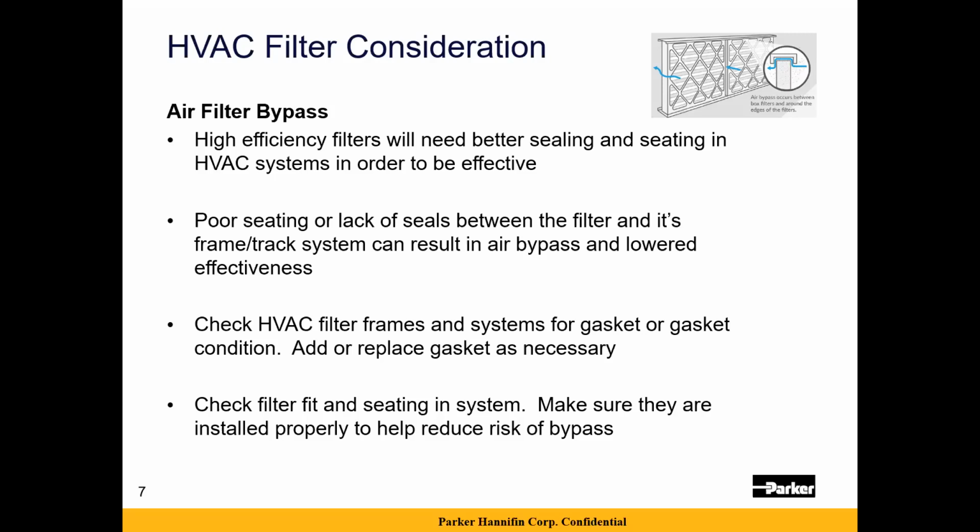The primary reason that happens is poor sealing or seating of the filter in its frame or track system. If you don't have the filter properly seated, sitting flush in the track or against the frames, then it can be sitting at an angle and allow bypass. Or if that filter is fitting loosely in the track, you can end up having bypass.